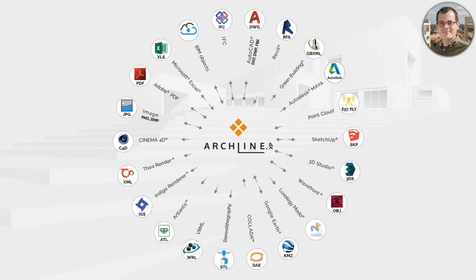The ARCHLine.XP import can be categorized in many different categories, but generally we are importing line work. So for example, DXF, DWG drawings. We have connection to other BIM software products, and that goes for our IFC or RVT or RFA file formats. You can also import PDFs, SKP file formats. So there are many formats, but two things to highlight here is the render connection. So we connect to many external renderer software. So if you already have a renderer software, that's not a problem, we can connect to it.